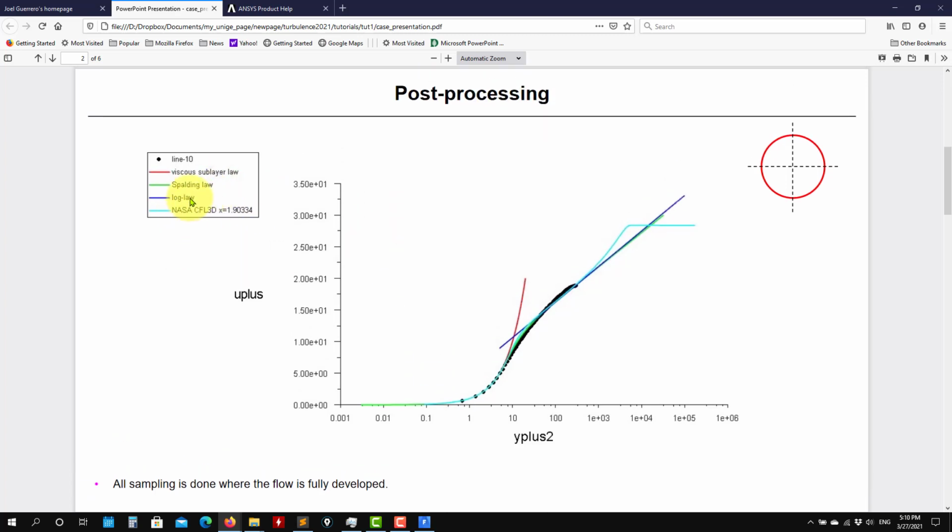But the interesting thing here is that see here that you have your theoretical correlations. And this is the output from another CFD solver. Different physics, I don't care. But remember, when you normalize everything, you should be able to reproduce this plot. What changes will change. Different Reynolds, you have different logarithmic regions. Okay. So that's all.